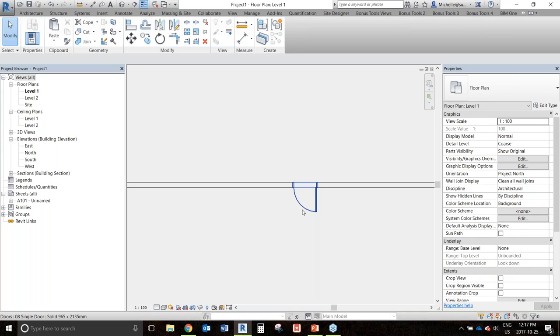So you have to be able to justify everything that you're doing when you're creating a family. To say, I'm doing it because it needs to show up in this 3D rendered view and we need it for the client. Or I'm adding this information, this data of all the information of a mechanical unit to the family because we're going to be scheduling it for the project. So whenever you're creating something as a family, you need to be thinking, I'm doing this piece because, and then have a reason for it.